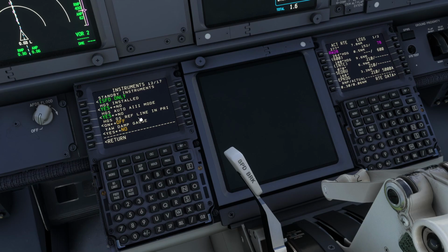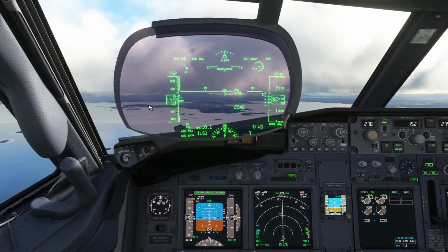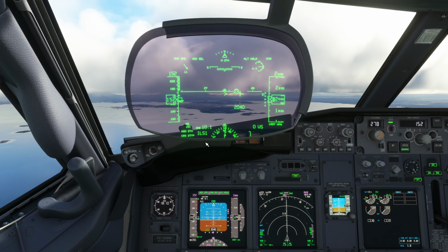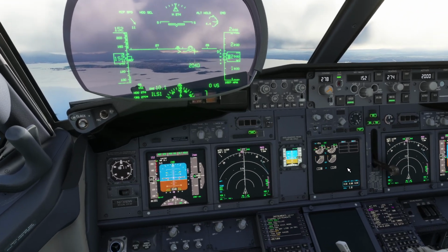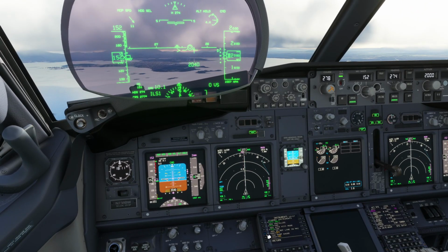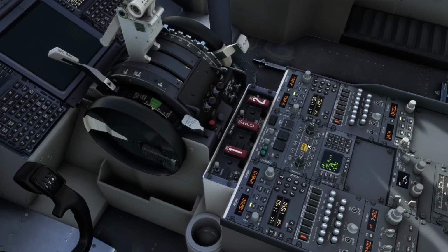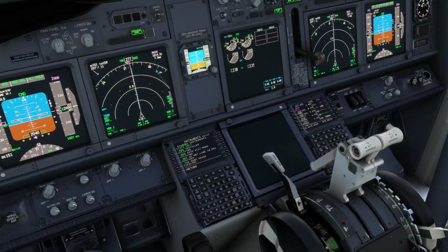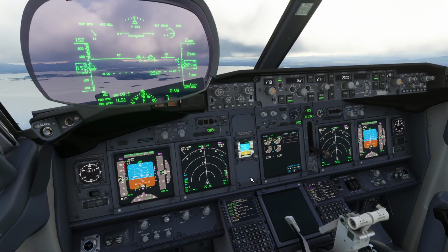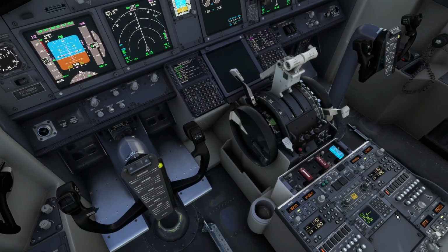So I'm going to show you how is our system now. As you can see, you have pretty much your primary flight display showed here. If you change this to on, you will see that another line is added to the system more or less around the radial altimeter here, and I'm going to show you right now. So to yes, and then you have the 3-degree glide slope angle here. Of course, this angle you can select and choose on this panel, but the main important thing is if you have this as yes, it will be shown every time that you are on the primary mode.